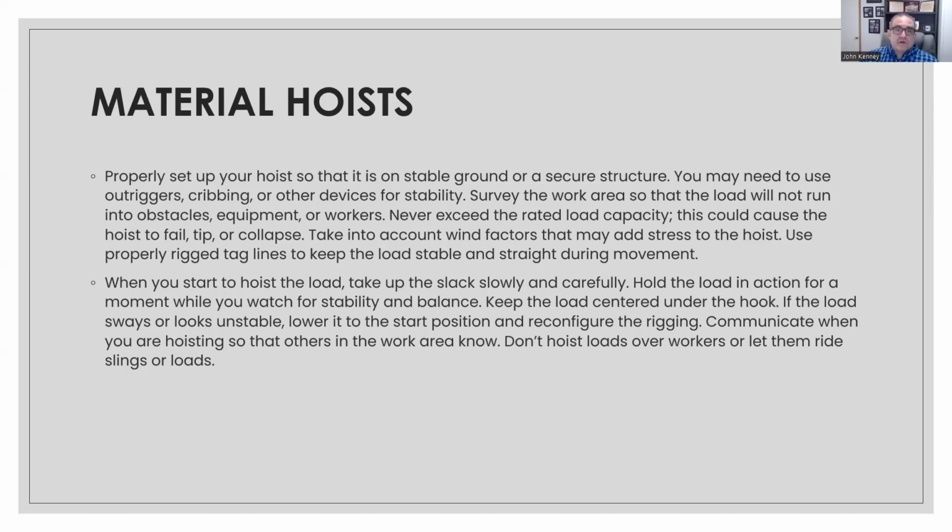When you start to hoist your load, take up the slack slowly and carefully. Hold the load in suspension for a moment. Watch the stability and balance. So again, whenever you're lifting, whether it is with a hoist, a power hoist, a crane or another means, you don't want to just jerk that load up. Make sure everything is rigged correctly and you don't have a problem with a loose connection, overload, twist, or bend that could cause a fall or the load to collapse onto the ground.